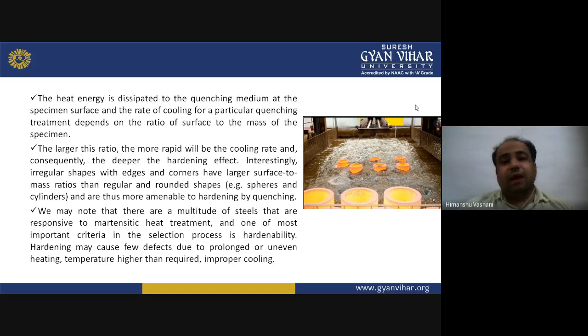The larger the ratio of surface to the mass of the specimen, the more rapid will be the cooling rate, and consequently the deeper the hardening effect.